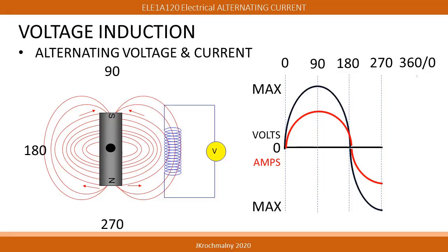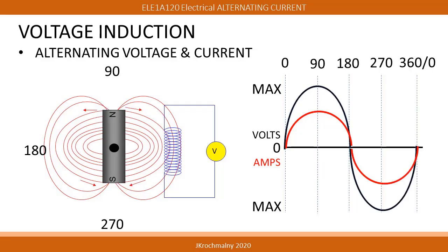Whether this voltage or amperage is located either above or below the 0 line on the measuring graph, it still represents power to the circuit using it. After 360 degrees of rotation, the process begins anew. This is perhaps the best example of what alternating current and voltage is and how it's generated.